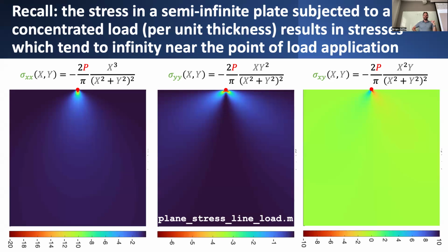We've assumed something pretty critical about the relationship between stress and strain, that it's linear. If you have, let's say, some relationship that looks like this, then this solution implies that for any, possibly even arbitrarily large, value of strain, you'll still get a linearly proportional value of stress, let's say in just the uniaxial case, that maintains this same linear proportionality as you increase the loading. So it doesn't actually matter how big you make the stresses or correspondingly the strains, but this is a big assumption.